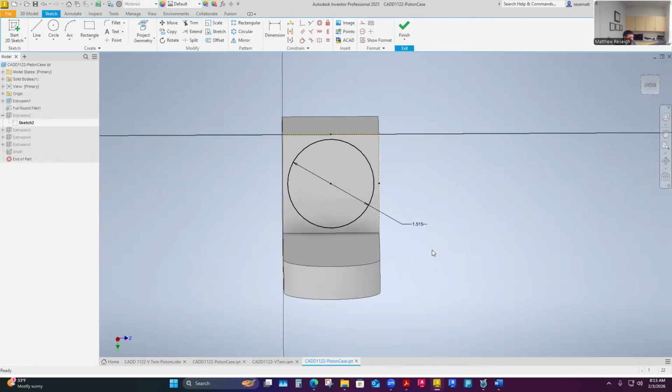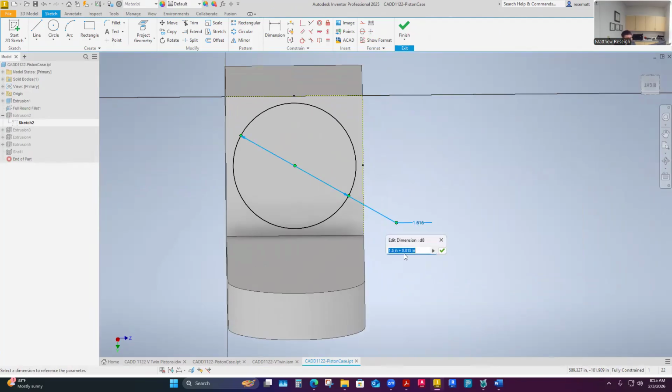So if I see here, 1.5 inches is what is scaled down from the original book exercise of 2 inch, so 1.5 inches. And then I've added 15 thousandths is what I've got. So that's really my actual dimension there. It would be like 1.515 essentially, what my dimension should show on my print.